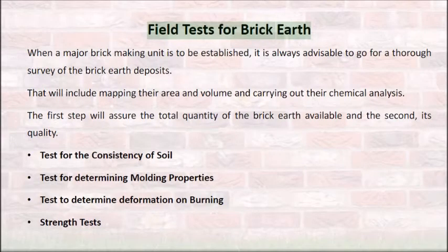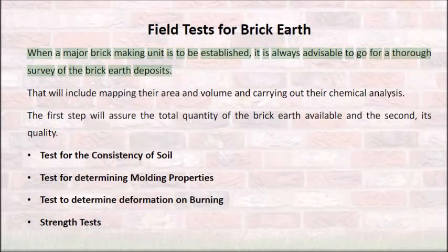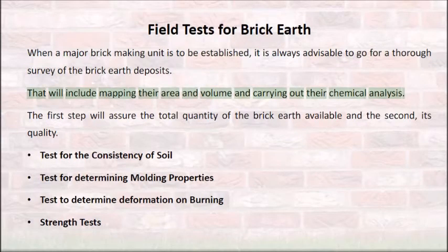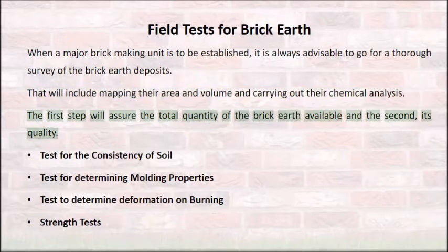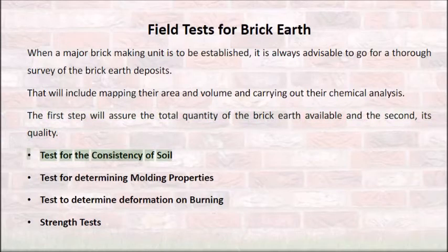Field tests for brick earth. When an amateur brick making unit is to be established, it is always advisable to go for a thorough survey of the brick earth deposits. That will include mapping their area and volume and carrying out their chemical analysis. The first step will assure the total quantity of the brick earth available, and the second, its quality. Test for the consistency of soil. Test for determining molding properties.